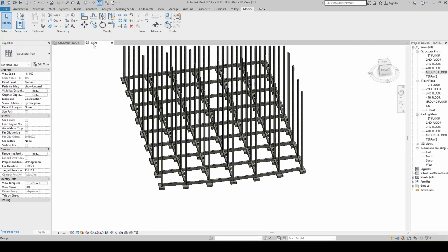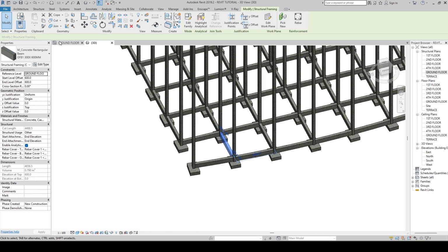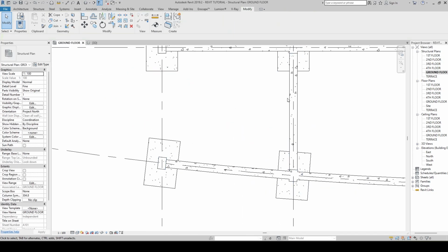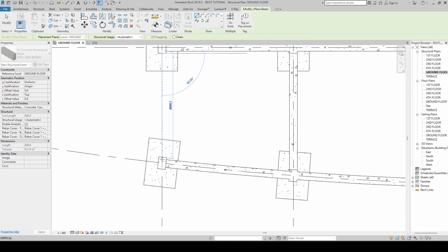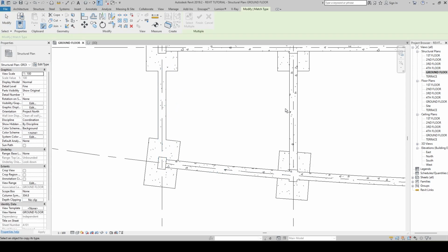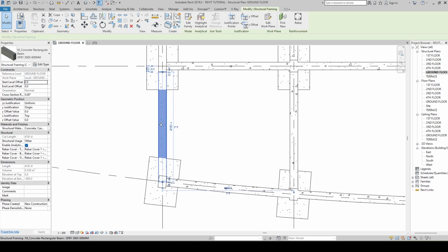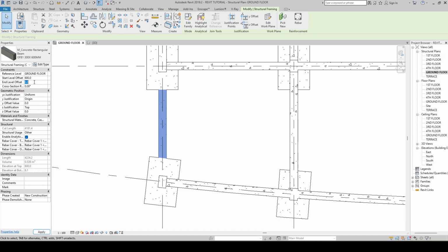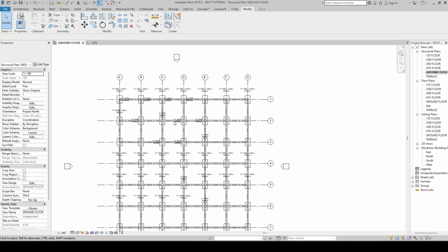Now if you go to the 3D you will find there's one more pending from here. I'll go to the ground floor once again, CS. I'll add the beams, connecting the things, and I'm closing it here, and I'll match the property. Sorry, it's not working. Let me do one thing. I'll keep the 600 mm at the top offset, and close. That's all. So now the beam layout has been taken care of very well.